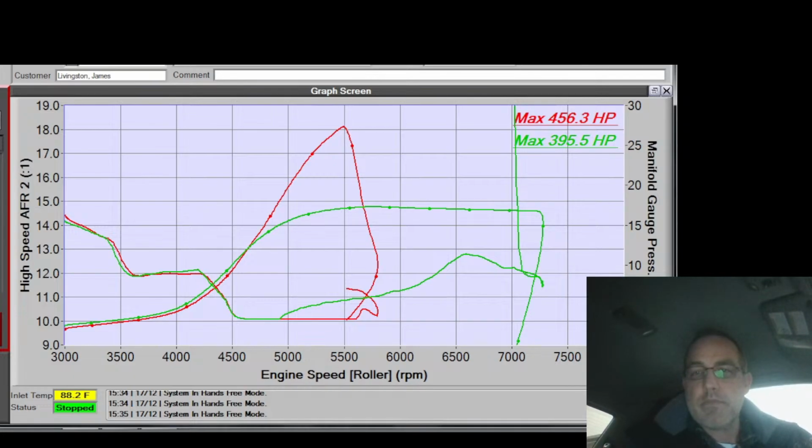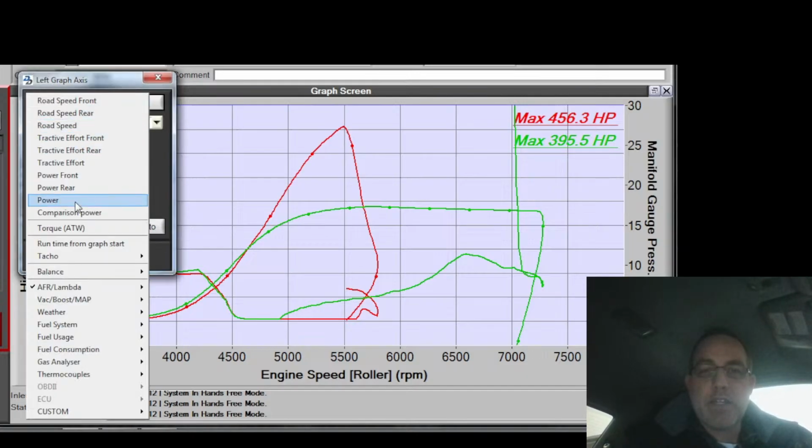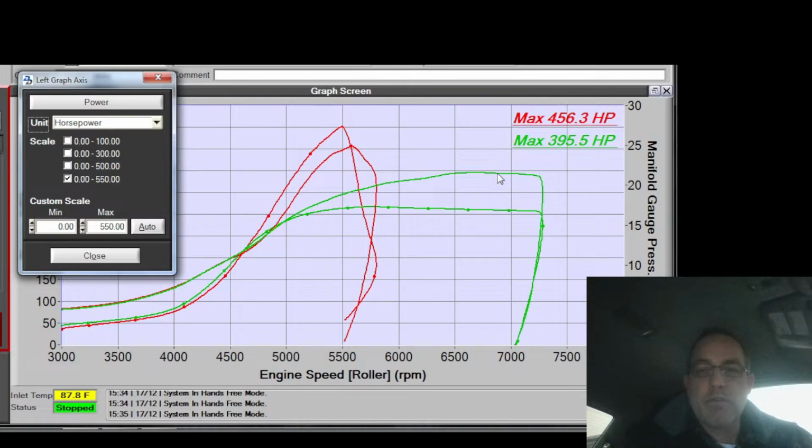So, auto airflow target is 256. Alright, man, I'm really excited. I'm actually excited that the VE is so much higher right here in this range. That is great. I'm looking at the cam timing, to see what it's at. But for it to be that much leaner than it was on the last turbo, that is great news. What does the power curve look like right there? Is it lean and mean or what? Oh no, it's nice and controlled. Little tiny spike, a little higher power right there. It was a little leaner, got a little cleaner burn. But yeah, look at that.